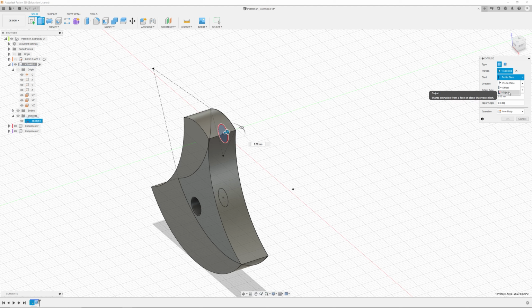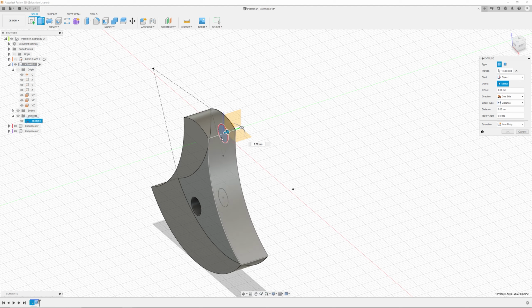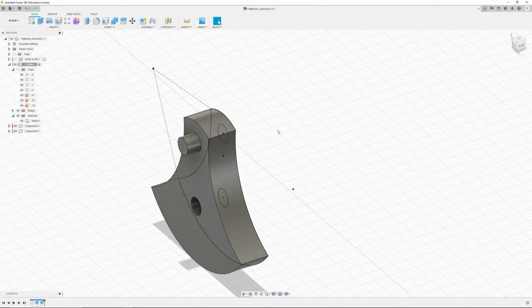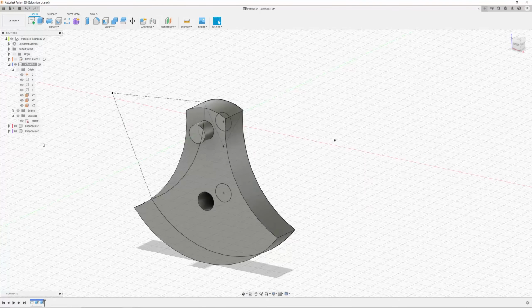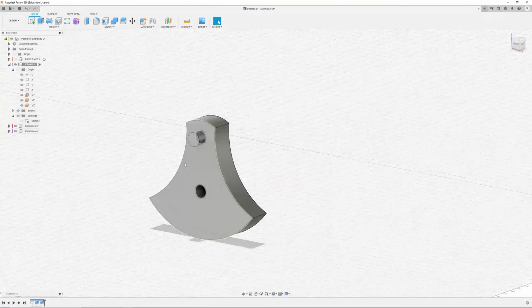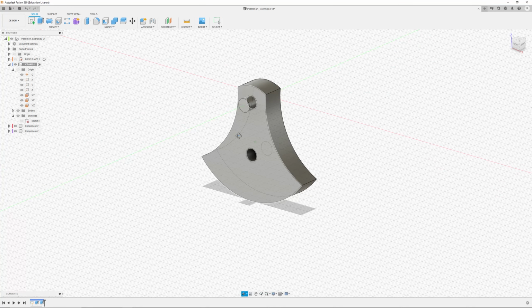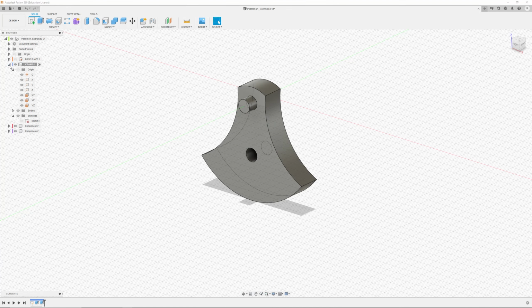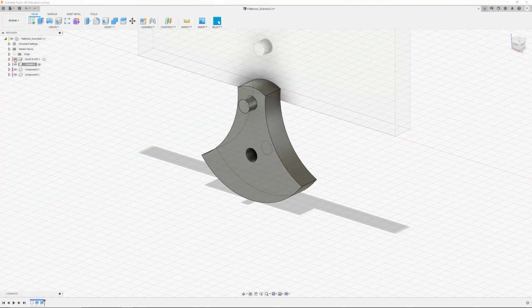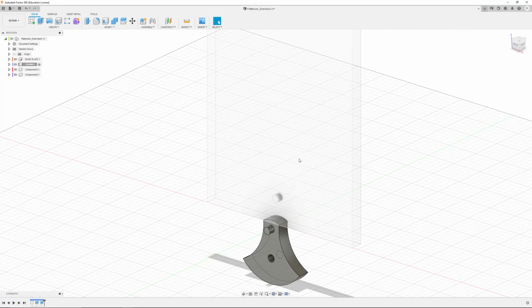So I'm going to go ahead and do Extrude here, which starts the extrusion from a face or plane that you select. I want it to start here, and then I want it to come out 5 millimeters, just like that. And I want it to join, so I'll hit OK, and then I'll go ahead and hide my sketch. And that gives me my crank. Everything there looks good, fully defined. Go ahead and drop that down, show my base, see where it is relative to the base there.